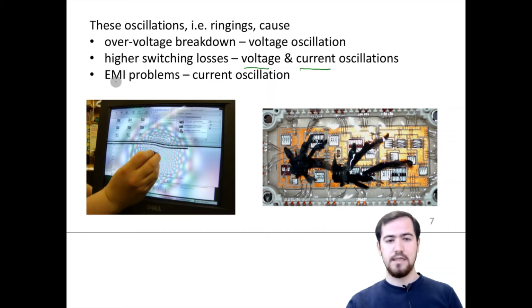And more importantly, it causes EMI problems, which means that our circuit radiates and couples to other circuits like analog measurements, digital signals, etc., and it distorts the other signals around them. An example of an EMI problem is actually shown here. I mean, it is just a magnet, but the magnetic coupling with the analog and digital signals inside this screen or the television causes some change in the color and variation in the image. So we need to solve these EMI problems in our circuits.